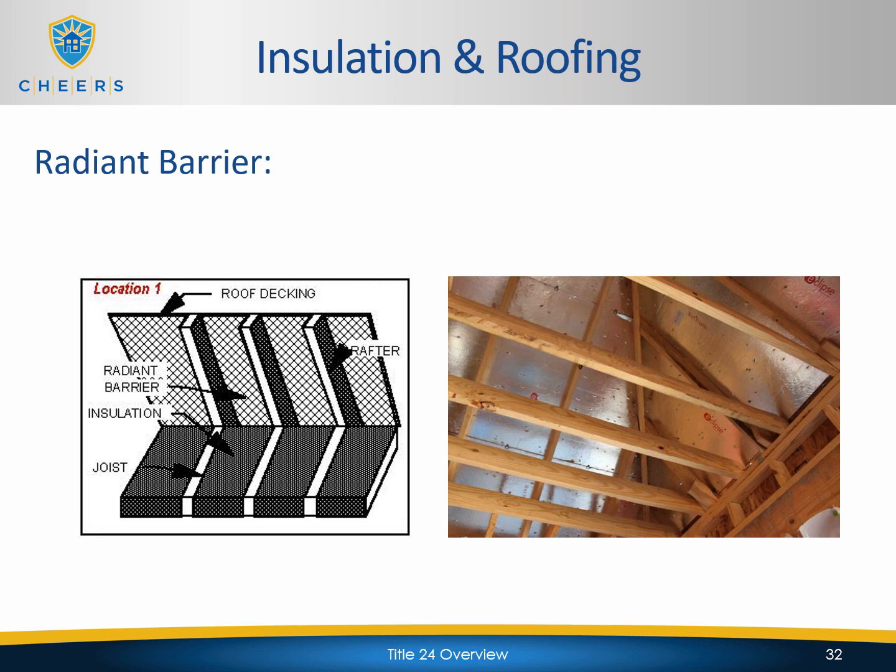So the first application, like I said, is pretty common in residential new construction. Basically the radiant barrier is actually part of the roof sheathing. It's installed just like a regular roof. The radiant barrier comes from the manufacturer on the underside of the roof sheathing and is then put on just like any other roof sheathing.